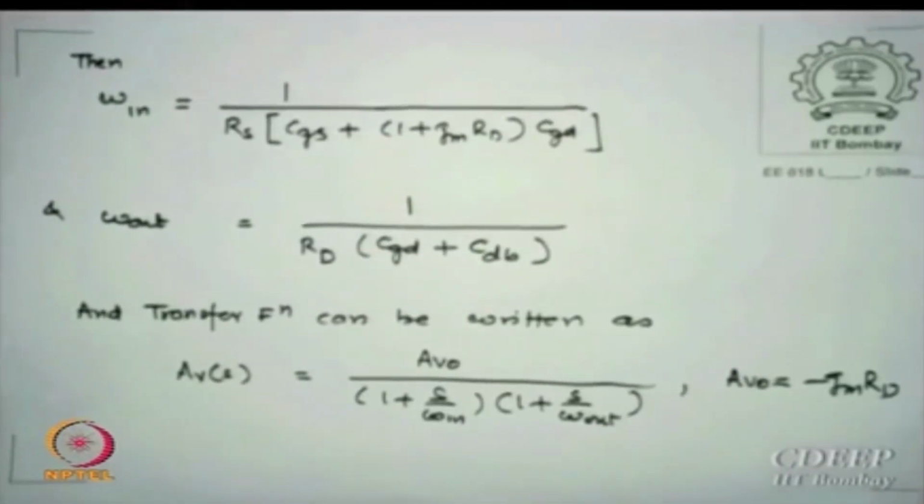But if you want to see approximately equal, then tricks have to be followed. Otherwise, as I say, if everyone does it with Kirchhoff's law there is no mistake, because SPICE doesn't make mistakes, you guys simply solve that network. So SPICE results and our results, but then why are we doing this? Because even to tell SPICE what omega I should start with, I should roughly get values, now this much bandwidth. So, a first order guess. Otherwise, step by step, you get the output after 1 million years. Okay. So this is typically what the transfer function looks like.